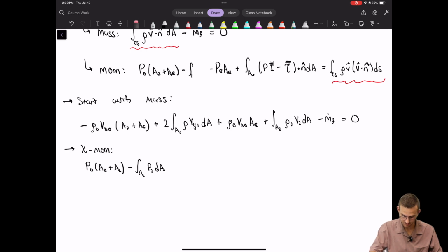So that's where it's being carried down here. Then of course we're also making that 1D assumption for the exits, which is fine. We also have that really ugly, fancy engine surface stresses term, so we have both the pressures and the shear forces being accounted for here, dot n hat dA.